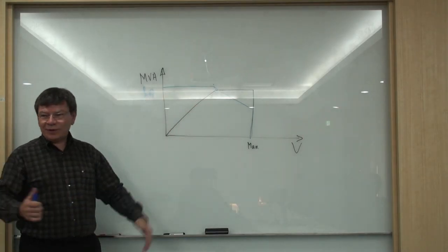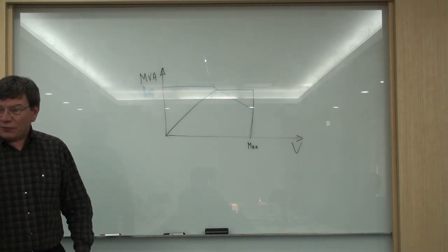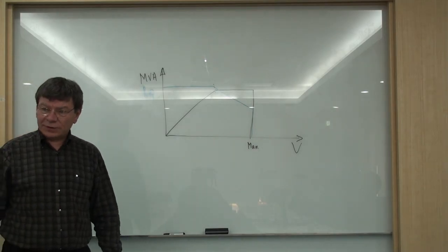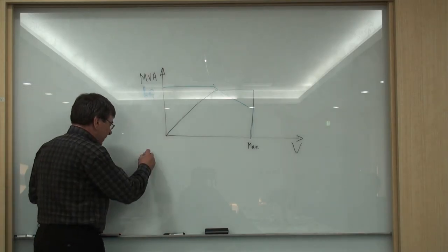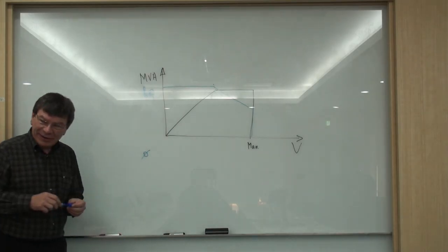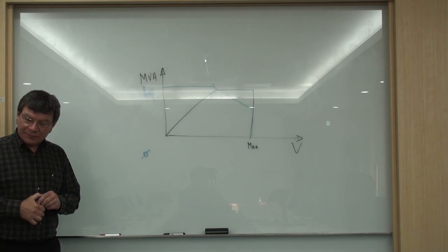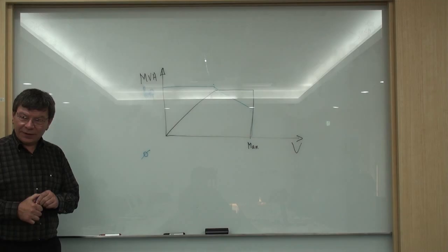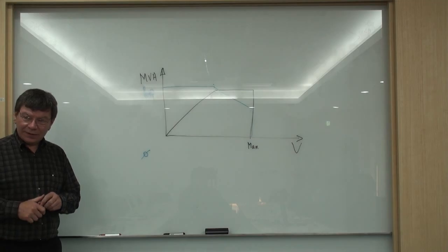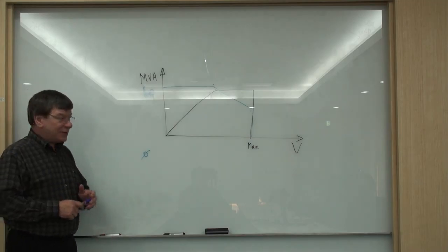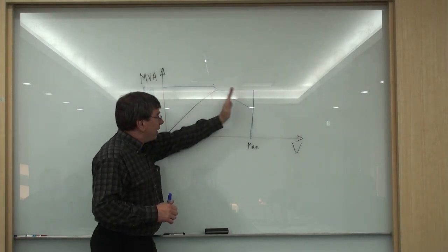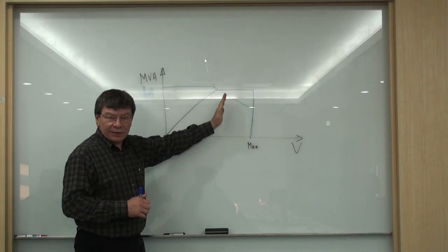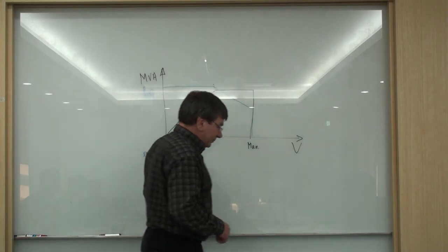The maximum current is giving you more or less the weight of copper you have to put in a transformer, because if you increase the secondary current, you have to have a bigger diameter to avoid overheating. So now everybody knows. Transformer, constant power area, constant current area.